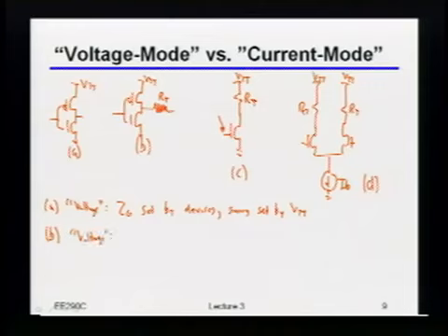Okay, so again, in this context, what do I probably mean by that being a voltage mode driver? Like, what are the sort of 2 criteria that I'm applying here? Or what are the 2 things that are being set by each other? Output impedance. Say that again? Output impedance. Okay, so now the output impedance here is being set by what? Device and RT. Say that again? Device and RT. Okay, so you're right, it is actually both the device and the termination resistance. But usually if I do this, I probably intended to set it by the termination resistance. Okay? Probably. That's obviously, it doesn't have to be that way, but that's probably what the intent was.